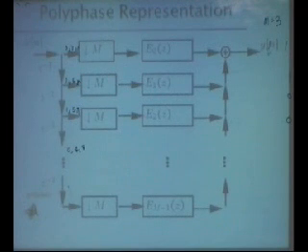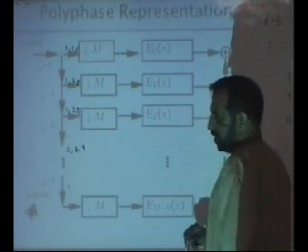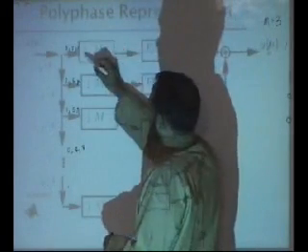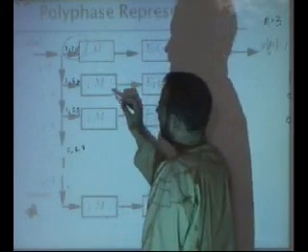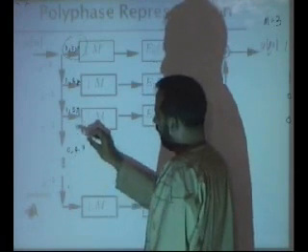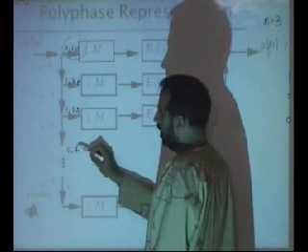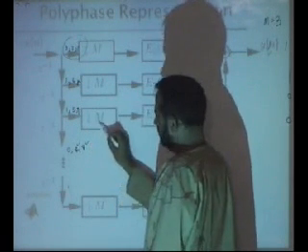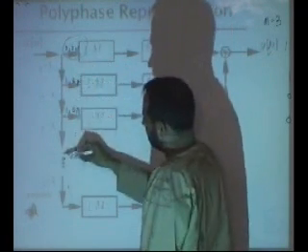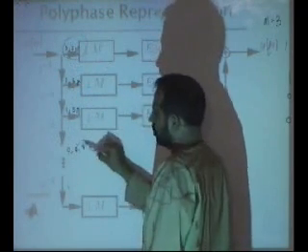So if this delay is giving 4 samples every time, why do we need this M then? What is this M doing? No, I'm saying effectively this M is doing this. Basically this M is saying that I'll keep 0. I'll keep 0, I'll throw away 1, 2, 3, then I'll keep 4. I'll throw away 5, 6, 7, I'll keep 8. So this is what the M is doing. The delay is doing this. It'll keep 0, 1, 2 and 3, but then it will throw away rest of the samples.